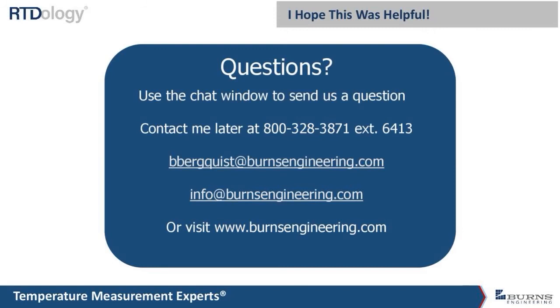Now, we do have a rule of thumb for a direct immersion sensor. So that's a temperature probe that has no thermal well or anything associated with it. It would be 10 times the probe diameter plus the sensitive length. So if we have a 1/4 inch diameter probe, that's 0.25 times 10, that's 2.5 inches. We add the sensitive length of the probe, which is typically about 1 inch. That gives us about 3.5 inches of immersion. That's what we would call a minimum to avoid stem conduction, and that's in liquids. Again, it's just a rule of thumb that covers probably 80% of the installations.